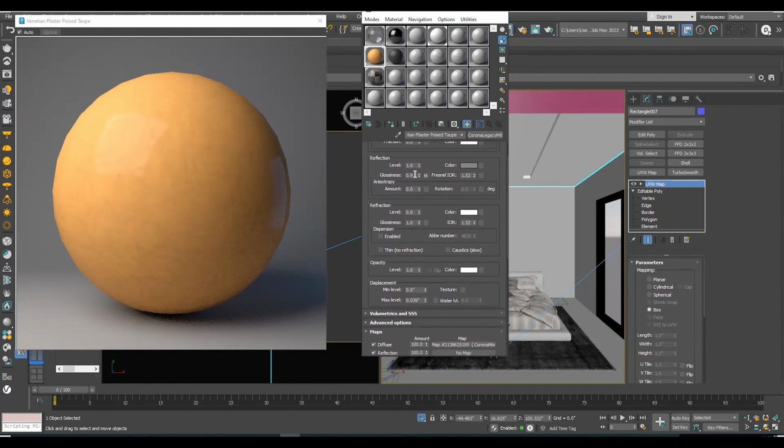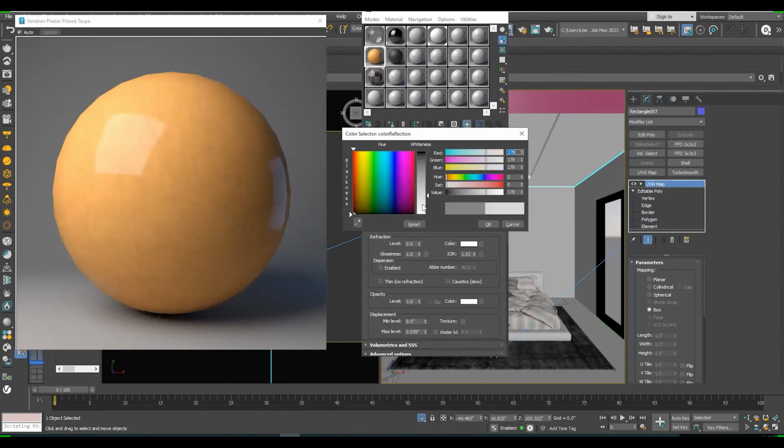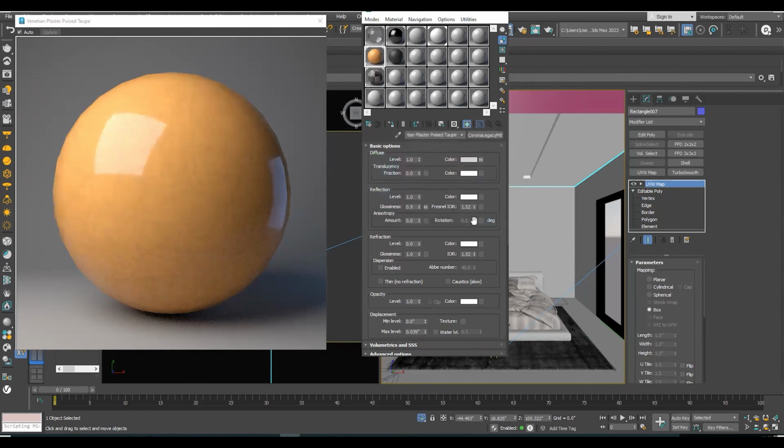Then you focus on glossy. So glossy basically works on the reflection. The intensity of reflection is controlled by glossy. So if I put 0.9, that means your reflection is more like a mirror or water, a more clear reflection. Okay. So if I put some more reflection, so when I make glossy about 0.8